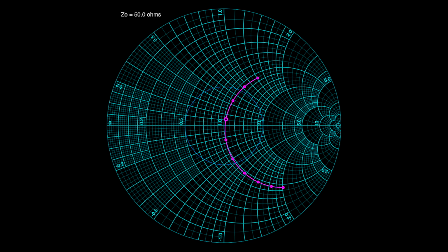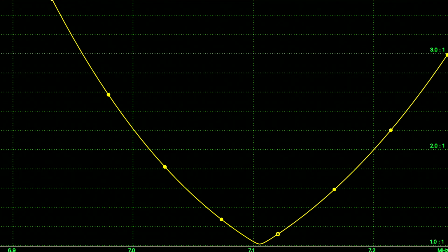We are using the vertical delta loop as a reference for our investigations. At resonance frequency, we get 2 maxima and 2 minima in the current distribution, as expected. Blue color means high current and low electric field strength, white means low current and high electric field strength. As on the lower antenna part, the electrical field strength is rather weak, the influence of ground on the impedance is bearable. It's running very nicely through the matching point in the Smith diagram, and the VSWR is ideal at center frequency.